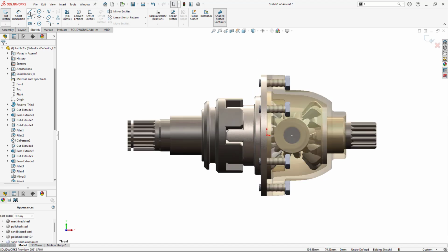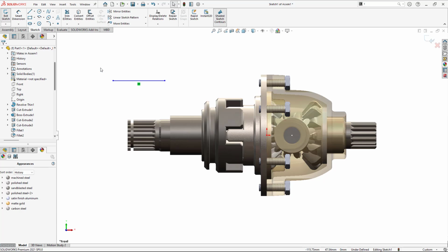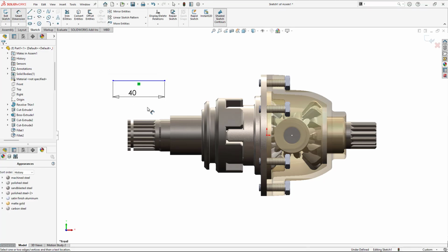And now if you would like to create a sketch, you could see there is no direct on-screen numeric input activated. If you want to give the dimensions, you need to create the sketch first, and then by using the smart dimension, you need to assign the dimension again. So to stop this repetitive activity, what we could do is,